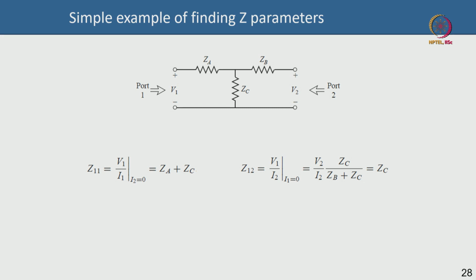Sometimes and oftentimes you have to convert the measured S parameter into Y parameter to do some manipulation, then Y parameter to Z parameter to H parameter hybrid, and then you plot the cutoff frequency. So, all the parameters are actually useful, because mathematical manipulation and mathematical treatment could be easier on some other matrix, whereas practical measurement is easier on the S matrix, S parameter matrix. This is the reason why all these different matrices are necessary.